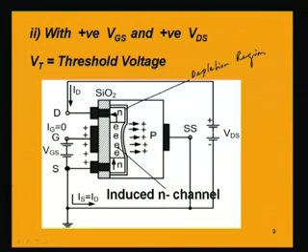So, although electrons are now induced in the N channel, these electrons will be crowding near this insulator, but they cannot be brought to the gate terminal by attracting them, because there is an insulating material in between. So, these electrons will not reach this gate terminal, they cannot complete the travel through this insulating material. So, there will be no gate current. The current which is entering this MOSFET will be leaving this MOSFET also. So, the drain current is equal to the source current.